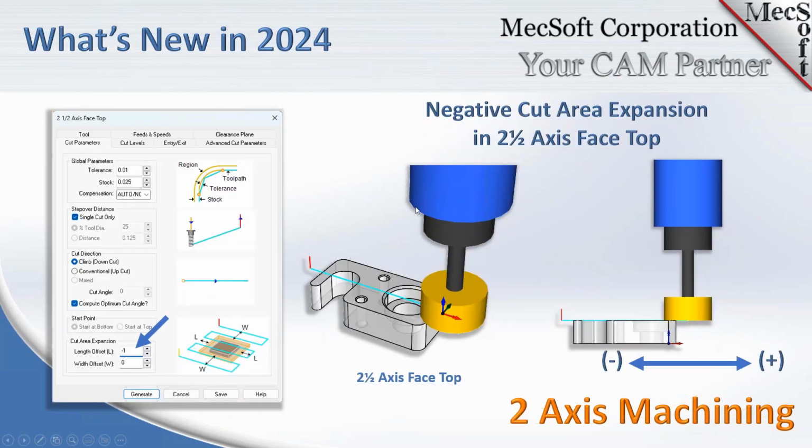Now here, this is a relatively minor enhancement, but it does contribute to maximizing the efficiency and reducing the time required to do machining. What you're seeing here is the two-axis face top operation, where the tool is just facing the top of the part based on the highest level of the part. As you can see over here on the right, we have a face mill, and it's just traversing left and right across the top of the part.